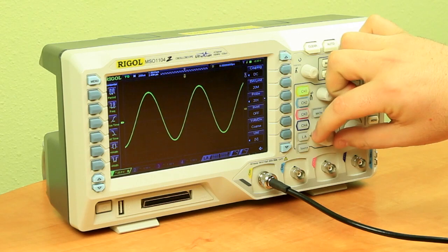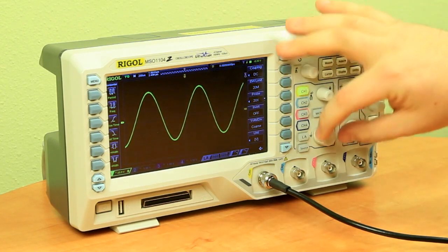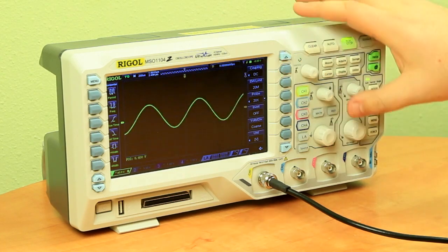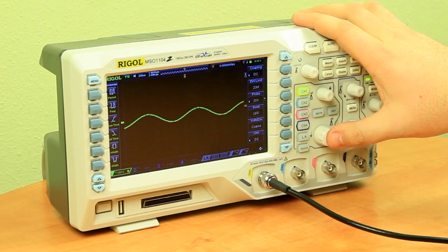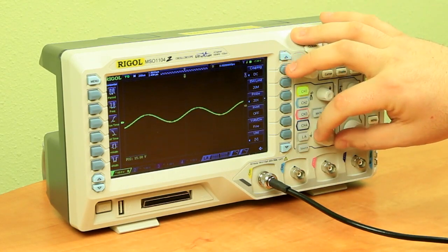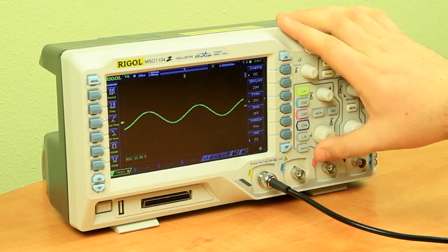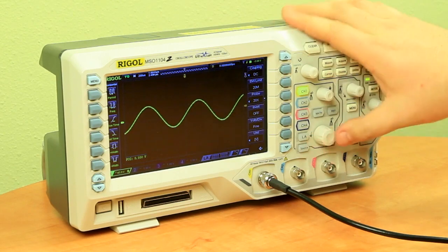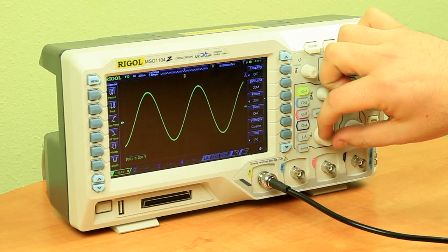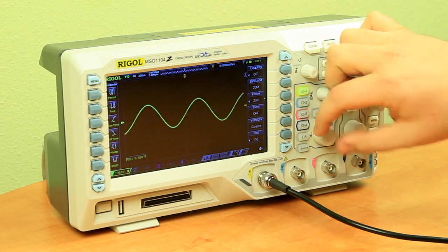Another aspect is we can change the scale of the particular signal by rotating this knob, and we can make it larger or smaller, and then we can also choose between coarse and fine measurements, which are displayed here. So right now we're in fine, so I can make smaller scale options, and I have to rotate a lot more to get a scale change. Or I can go with coarse options, which are more of the presets, which will let us snap in between much larger scale positions.